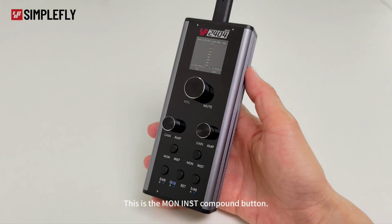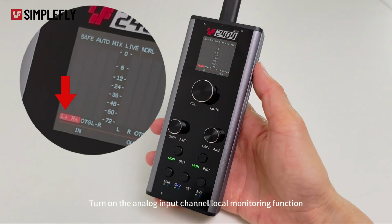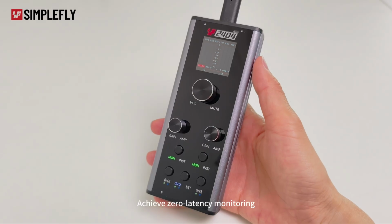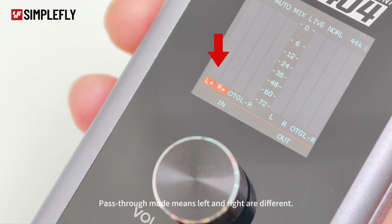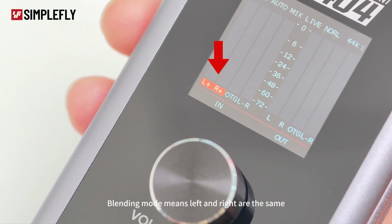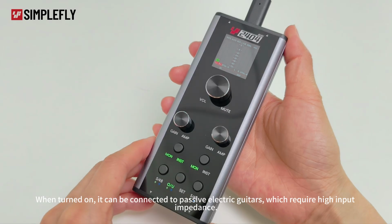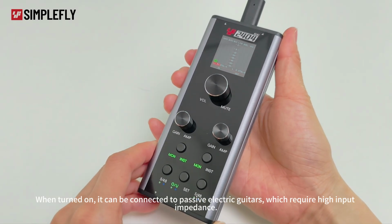This is the Mono Inst composite button. Short press the button, the Mono indicator light is on, turning on the analog input channel local monitoring function. It routes the input signal directly to the monitor headset to achieve zero latency monitoring. Double-click the button to switch the local monitoring mode. Pass-through mode means left and right are different. Blending mode means left and right are the same. Long press the button, the Inst indicator light will light up, and the Inst function will be turned on. When turned on, it can be connected to passive electric guitars, which require high input impedance.